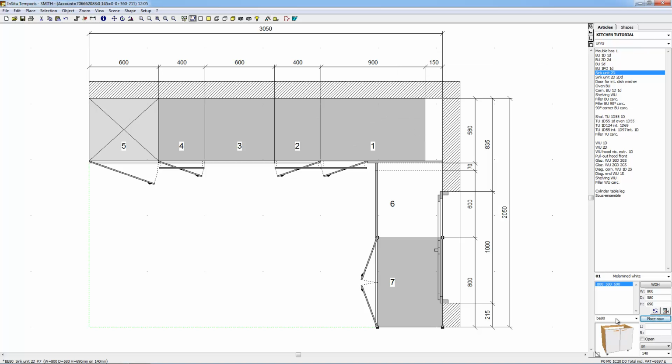Let us move to the vertical plan of the 3050mm wall, the wall without any window. To do that, select the 3050mm wall by clicking inside the wall, and take care not to move the mouse between the click down and the click up. The ends of the wall should flicker. If that's not the case, do it again.